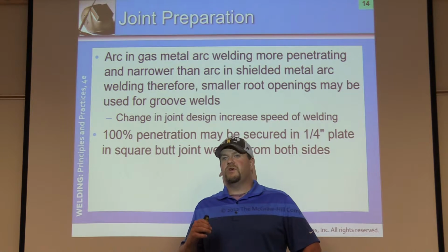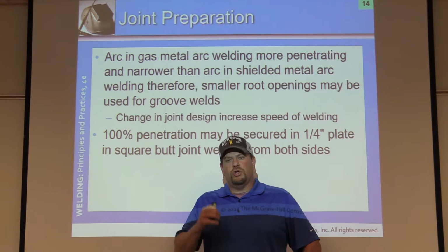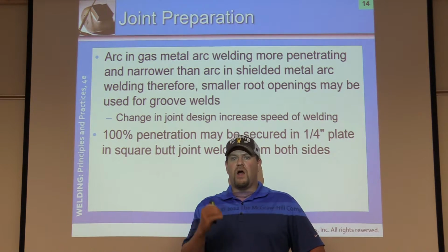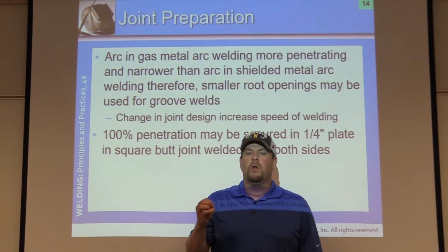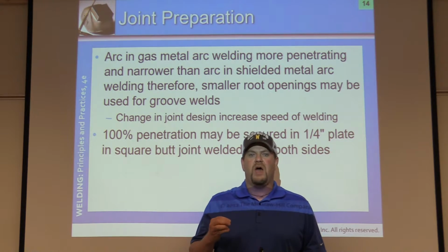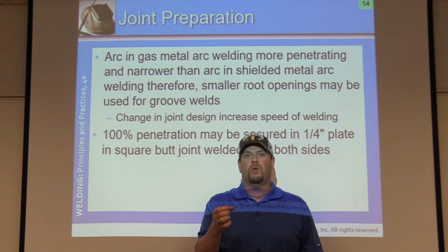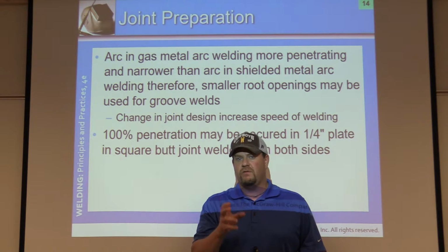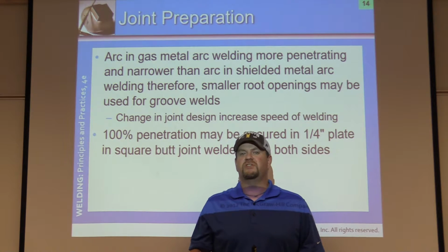What I want to stress upon you the entire time in this welding program is you weld to a good weld bead. I don't care how heavy or how thick it is. There are things that matter a lot more than doing a weld in one pass. Number one is fusion, penetration, a good weld that is acceptable. You weld to the weld puddle and the performance of the filler metal and process you're using, not to what the machine says it can do.